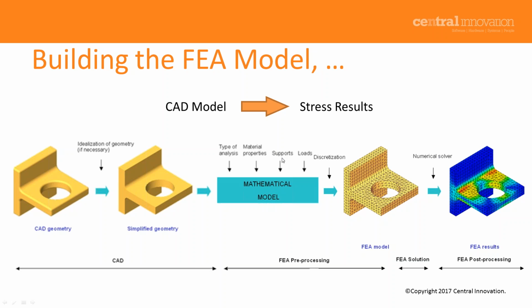Then, how is our actual design connected or related to the rest of the world? Supports. What sort of working conditions we have: pressure, force, let's say temperature, etc. So it's coming to loads. When you answer all of these questions, you have prepared your FEA model, and we can see the pre-processing stage is simply completed.